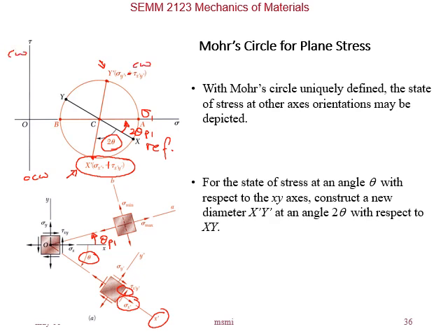So you draw clockwise components of the shear, okay? And then the normal stress on this plane, y plane, will be from this coordinate here. So it's sigma y prime. So just put sigma y prime there.